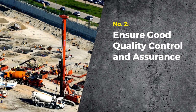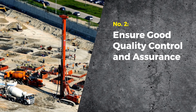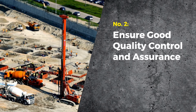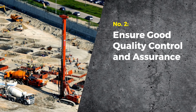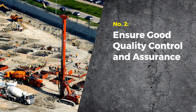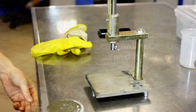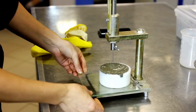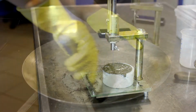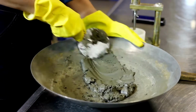Let me explain. Concrete producers design concrete mixtures to meet the needs of the contractor in terms of workability, for example, flowability, pumpability, finishability, and so forth, based on their local aggregates and then using sufficient quantity of cementitious materials to achieve the required compressive strength, which is higher than the specified compressive strength. This overdesign, that is, the difference between the actual average compressive strength and the specified compressive strength, is based on well-established statistical methods described in the codes and standards for concrete.